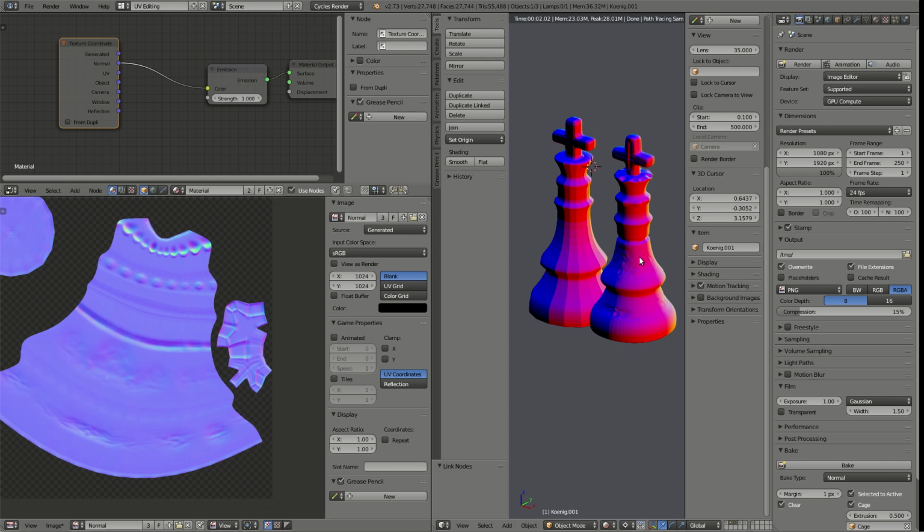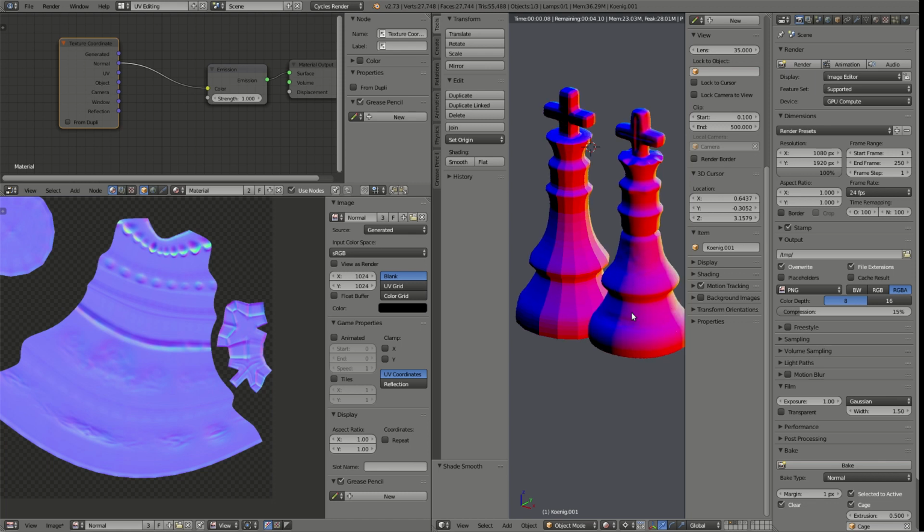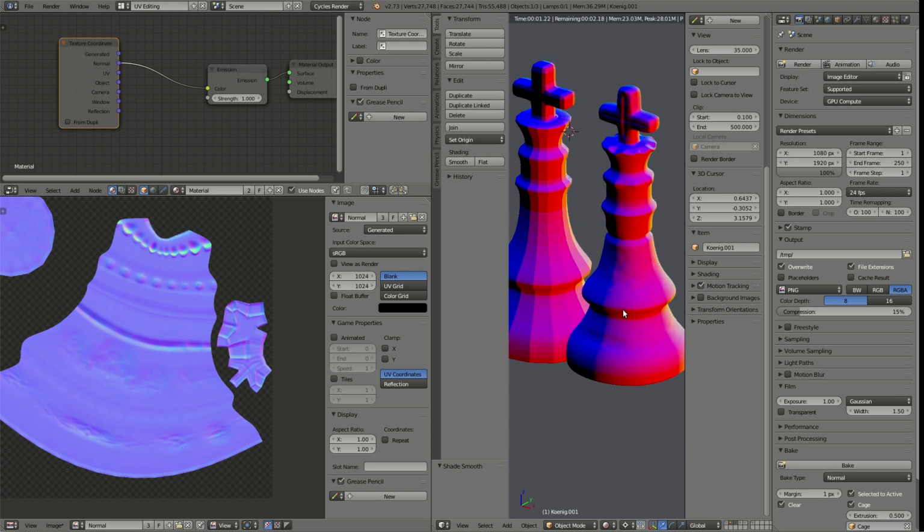And there's another thing we need to do, and that is we need to set the shading to smooth, because now you see things are smoothed out and we don't have the direction of faces anymore, but of every shading point, because everything else, the directions get interpolated now.